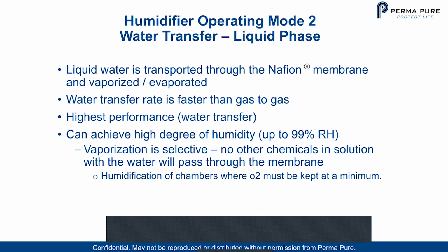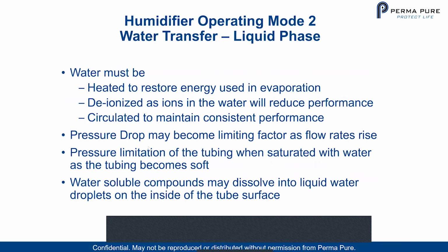So this is very important to understand that this is very selective and has very high transfer rates. But there's a couple of caveats here. First of all, the water must be heated to restore energy used in evaporation. So it's not energy free. You need to continuously heat the water, because the evaporation is going to chill the water left behind.